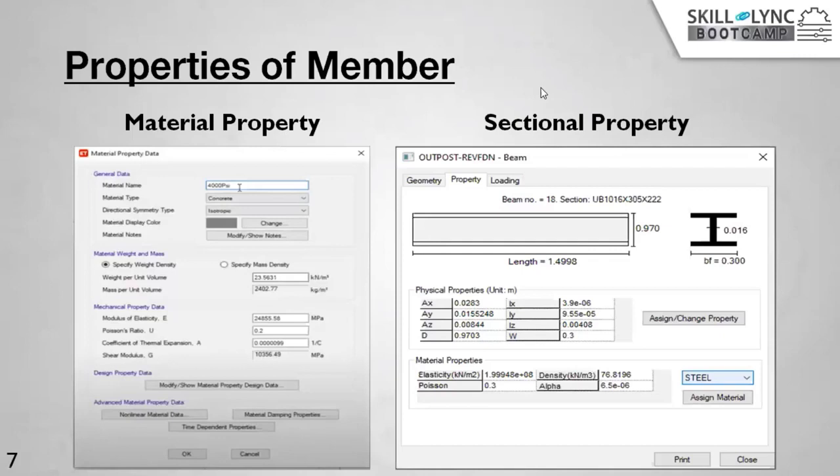Because in a case, if you are providing a 600 depth beam, you analyze and you get some forces, which requires a 1 meter depth beam, you cannot simply design and sell it. You have to reanalyze the structure with the 1 meter depth beam, since the member stiffness will take effect in the analysis. The stiffer the member, the more forces it gets.